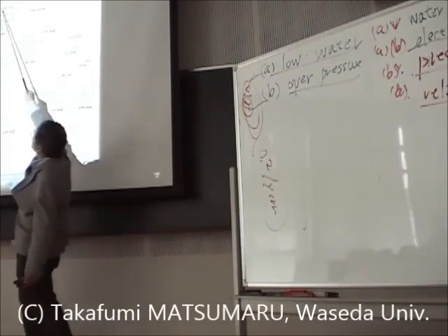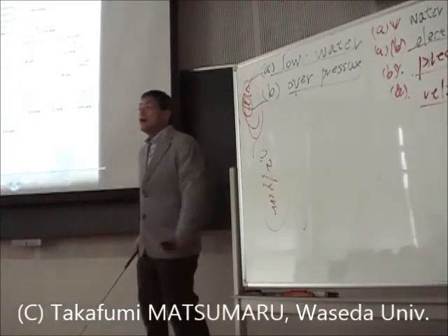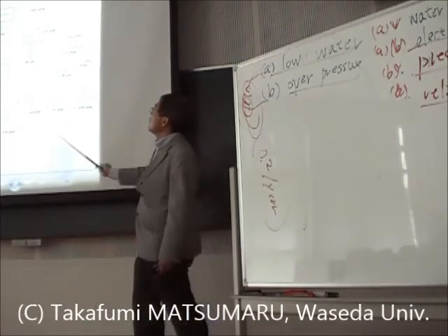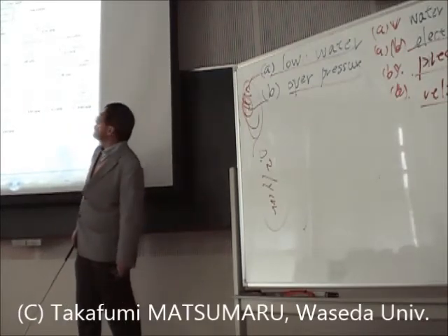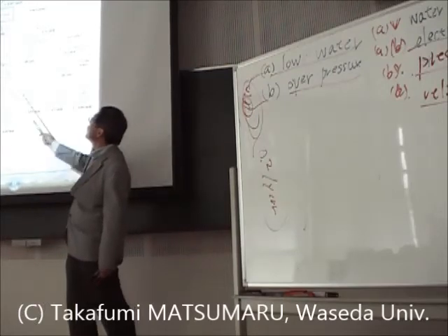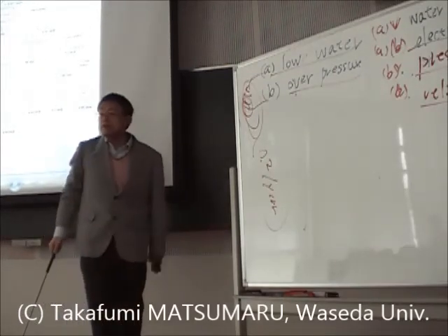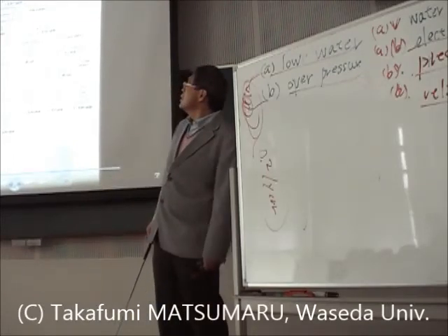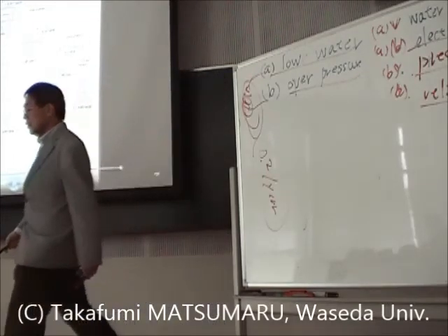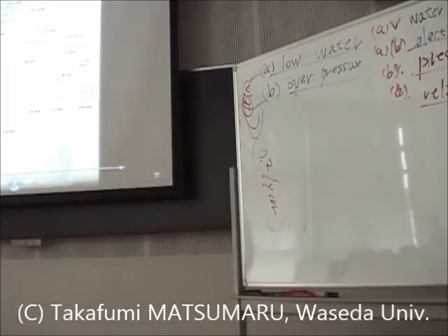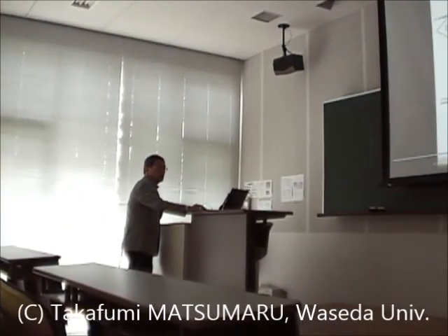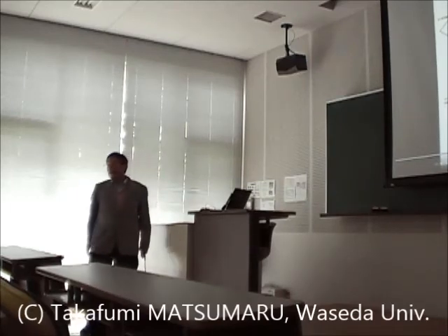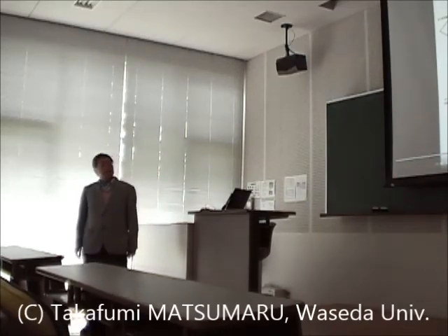And to get the frequency for the operator injury, we have an AND gate here, so rather than adding them, for an AND gate we multiply the frequencies. So the frequency is 0.2 times 0.35, giving us a frequency of 0.07 per year, which is the answer to the question. So to get your marks for this question, you need to draw a full tree that looks something like that, and calculate all the frequencies at each of the level events, and calculate the frequency of the operator injury at 0.07.